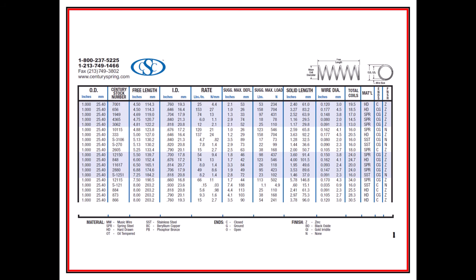Anyway, continuing, here is also a catalog page from Century Spring, where we can find a whole bunch of different information that we care about, like the spring rate. That's the stiffness. They are cataloged by order of the outside diameter, and then going down by free length of these off-the-shelf springs. They also give you the inside diameter, and over here the wire diameter. So that's something we want to know. The total number of coils, the kinds of ends, right here. They have closed, open, closed and ground, and open. Sometimes the closed and ground, CG, are right there, so you know that exists.